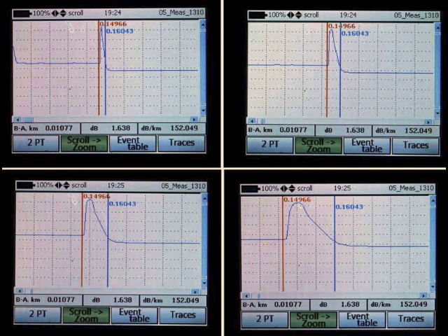By choosing the appropriate pulse width, you can get the best resolution and distance trade-offs on every trace. But you need to know how long the cable plant is and how the OTDR trace will be affected by the pulse width in order to make the right choice.